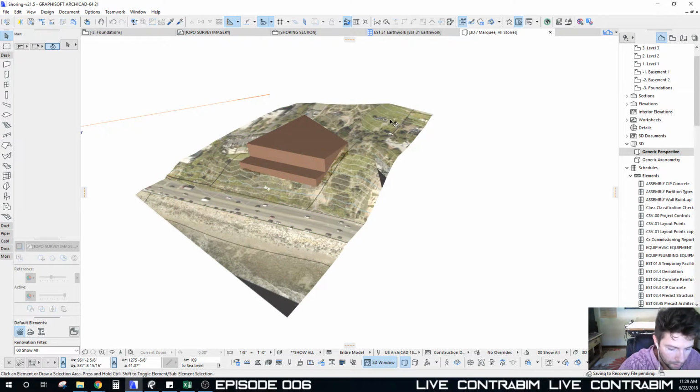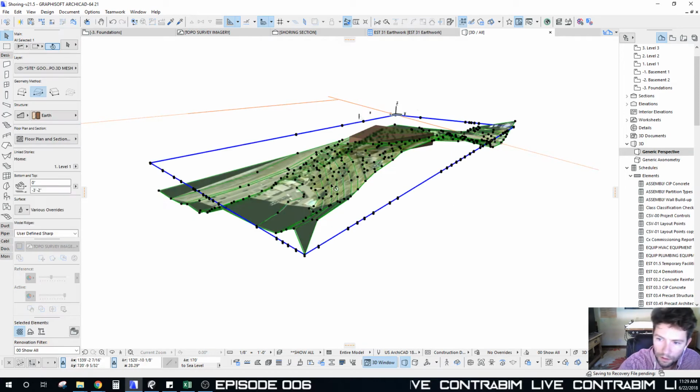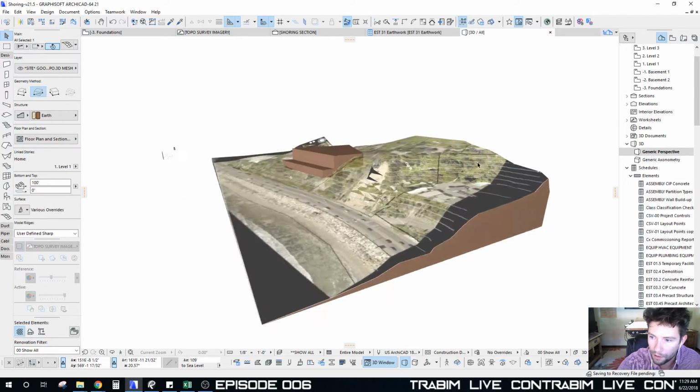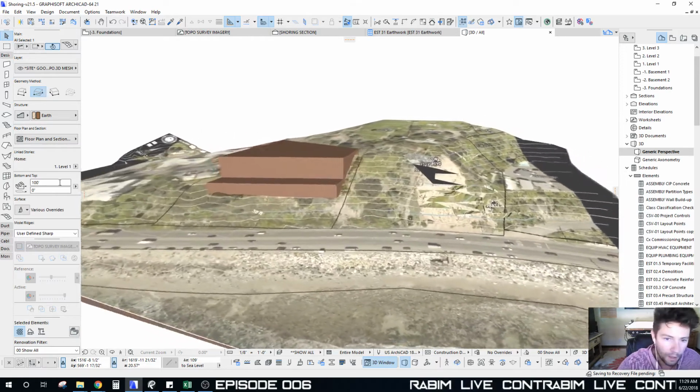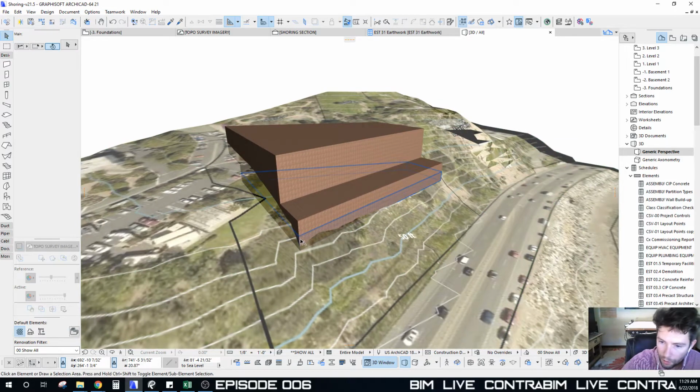That's a little strange, we're not seeing the edge of it. What's going on there? Oh, so my base level here on my project 0, let's actually turn this to a C level. So my base level, I need to set that down to 0. That way we can get our full thickened volume all the way down. So that was our issue right there, why we weren't seeing the full thing. Okay, so there we go.